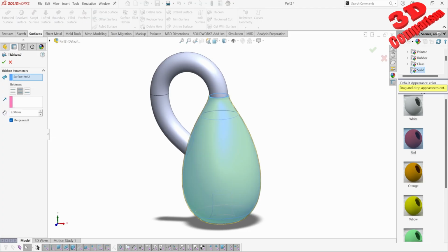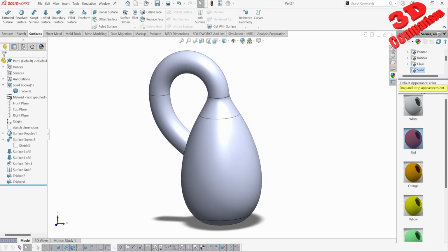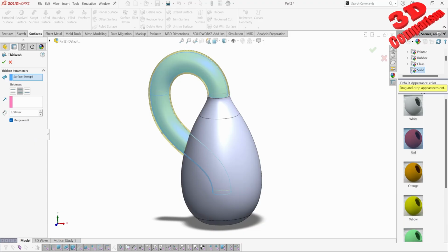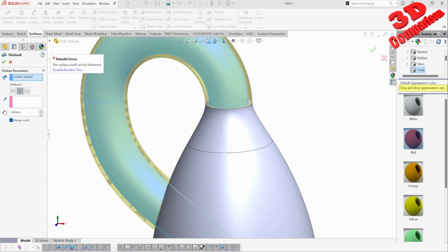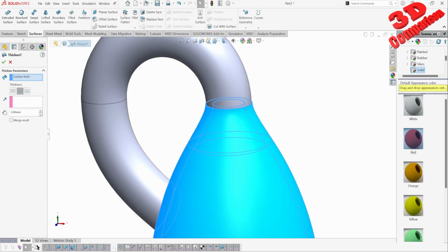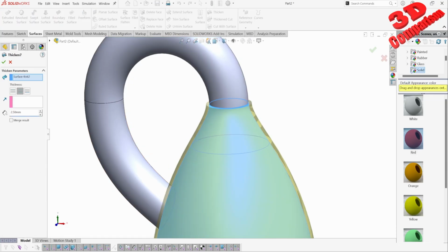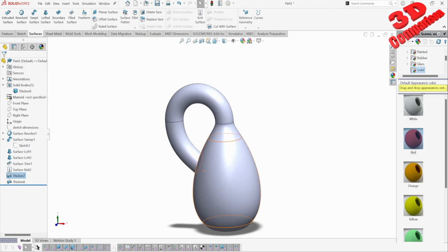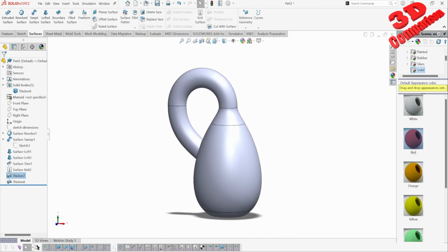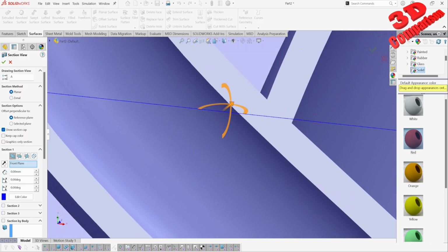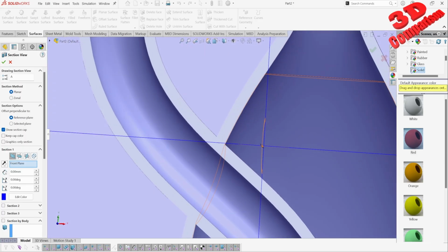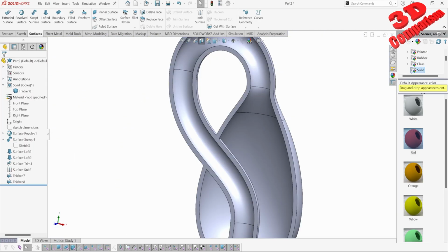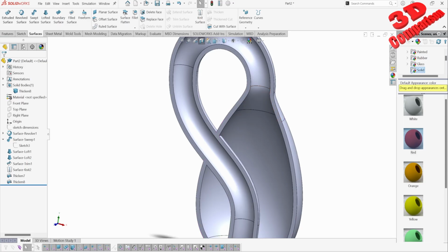Now, if I were to increase this to 3 millimeters, we're going to see that this will be the main problem. If we're going to go with a lower value of 2.5, considering the current geometry, this should also work, but afterwards that 0.5 millimeter will not work. So keep that in mind if you are trying to design this bottle. With 2.5, we see that the overlap over here will work perfectly, and we can start adding the final finishing